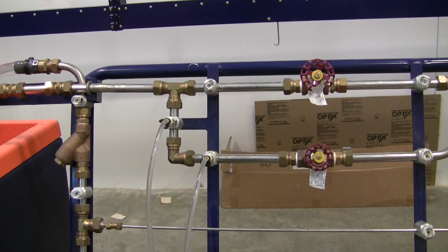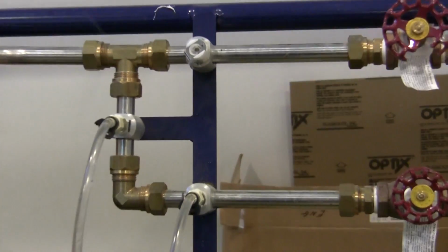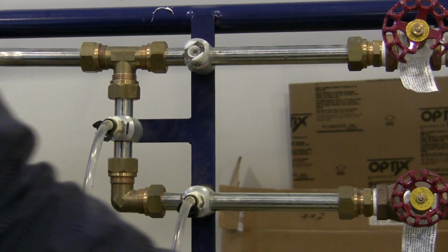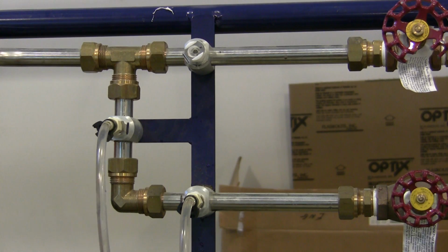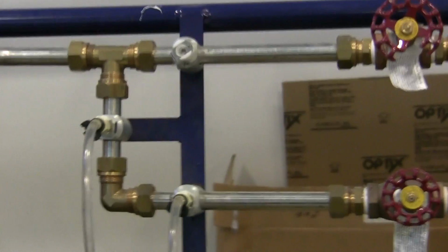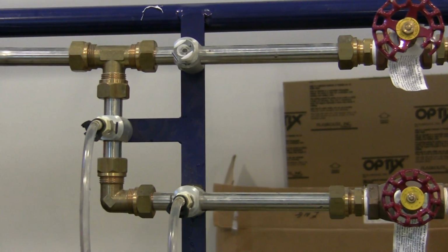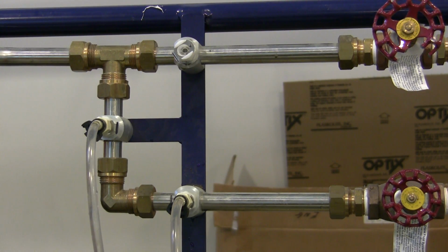Taps are clear and open for business. I can get a pressure measurement through that 90-degree fitting now. So let's plug it back into the pressure measurement meter. All right. Turn it on, and let's see if we can get a zero. Lots of water on the floor. I'm going to take a moment to consider my safety and the safety of others, mop up this wet concrete so that there's no slips, trips, drips.